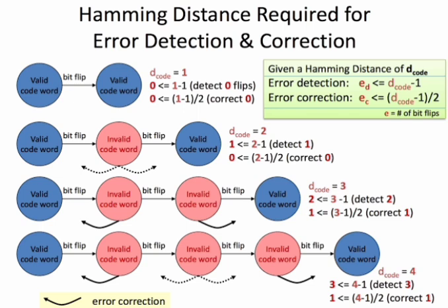Superheterodyne receiver. Superheterodyne receiver is used in AM receiver circuits. AM radio broadcasting utilizes the frequency band 535 kHz to 1605 kHz for transmission of voice and music. Carrier frequency allocations range from 542 kHz to 1600 kHz with 10 kHz spacing. The baseband message signal is band limited to 5 kHz. Intermediate frequency used for AM is 455 kHz.